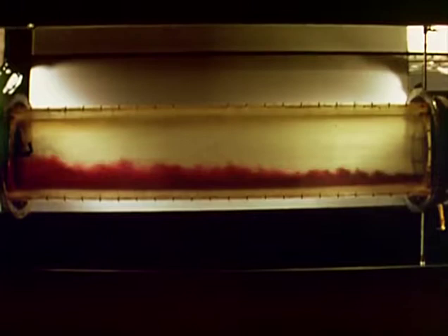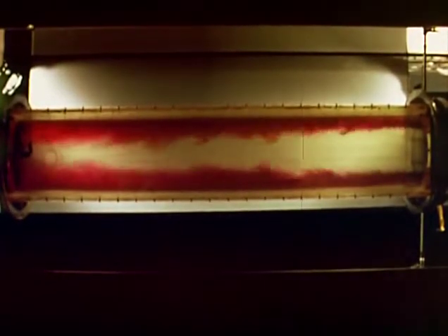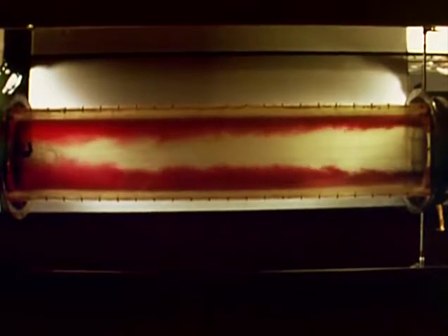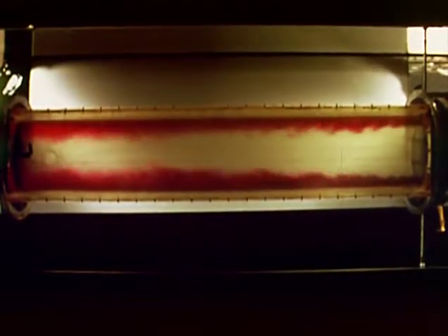You are now looking vertically upward at the flow. There are 2 injectors from opposite sides of the pipe. The 2 injectors are extended to 1 1/2 inches. In this and the following scene, the velocity has been increased to 10 feet per second. The nozzle extensions are 3/4 of an inch and 1 1/2 inches.